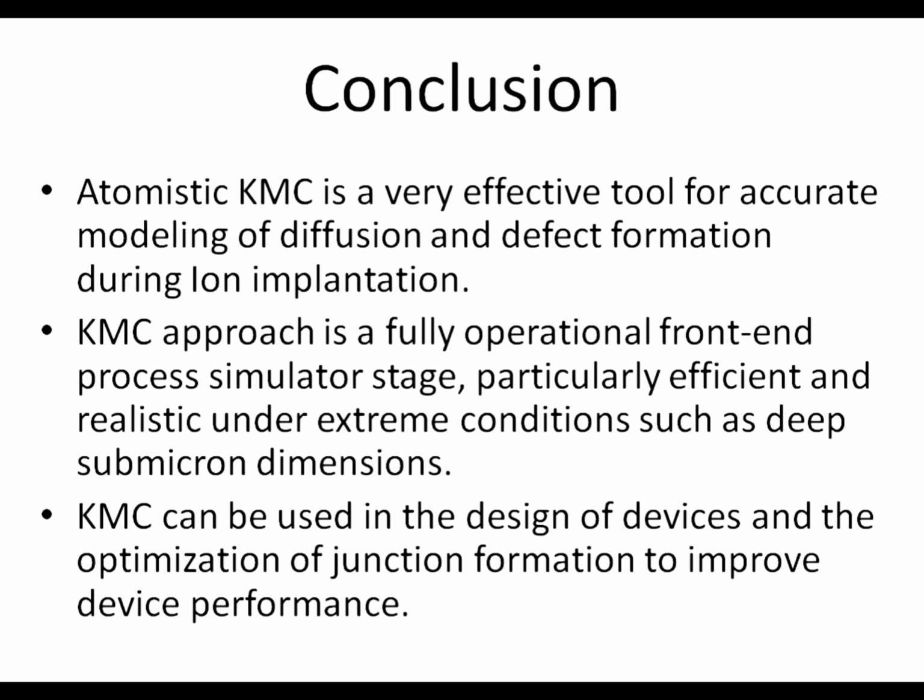Atomistic AMC is a very effective tool for accurate modeling of diffusion and defect formation during ion implantation. The AMC approach is a fully operational front-end process simulator stage, particularly efficient and realistic under extreme conditions such as deep submicron dimensions. AMC can be used in the design of devices and the optimization of junction formation to improve device performance.